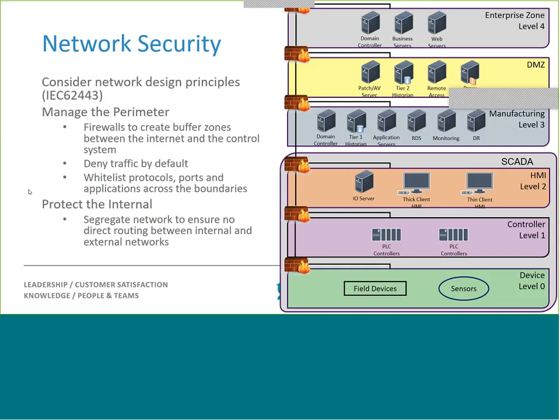This is a basic, simplified network design for the zones we are talking about. Based off ICS-CERT, NIST, and ISO standards, we have utilized the Purdue model for zone segregation and firewall security. This is our current example of a structured architecture. Depending upon your specific system and requirements, you would most likely need to make adjustments to this. The key, however, is understanding what you currently have, and then looking at what the simple, low-cost steps are to start moving towards a structured, secure architecture.